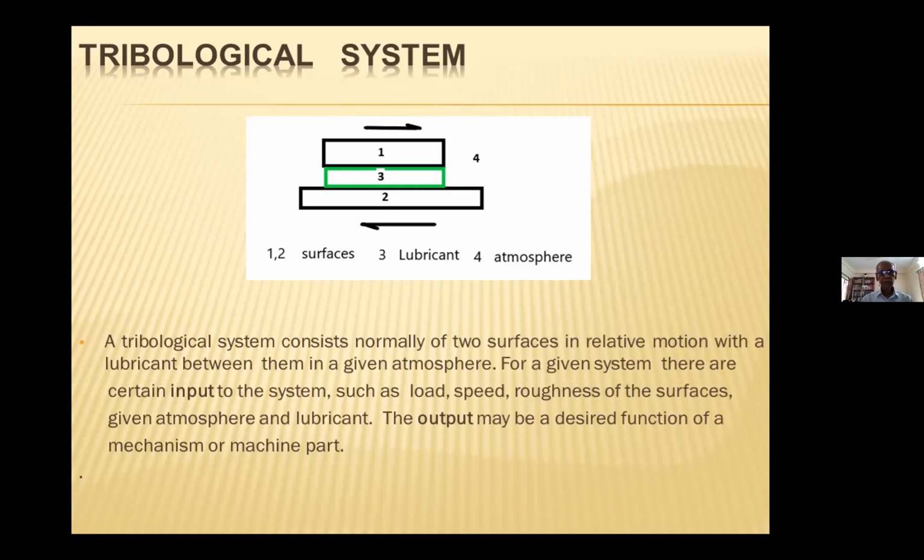Whereas if you slide the two surfaces in air, you'll find it's not so difficult, because the atmospheric contaminant acts as lubricant. You don't need to put a drop of oil. There is enough atmospheric contaminant which contains oil and many other contamination which would act as lubricant. We'll know later on this is called boundary lubrication, and that acts well.